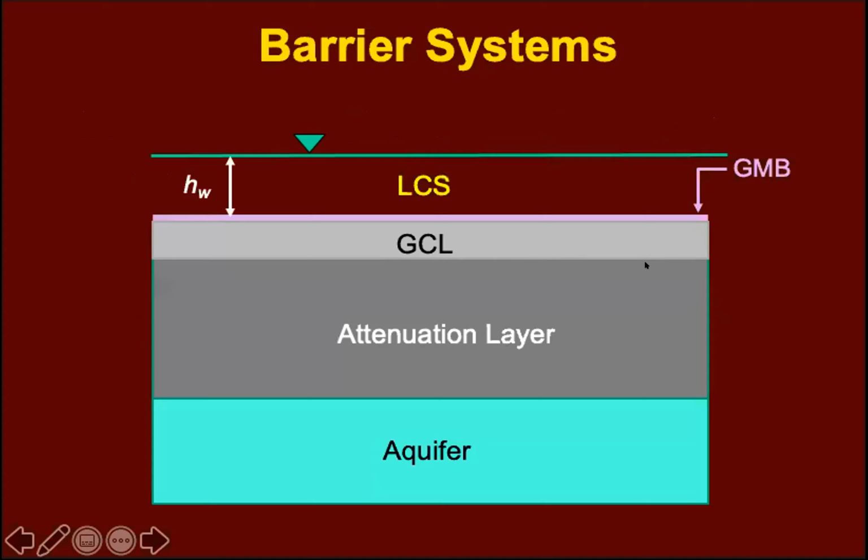The presence of a leachate collection system is not enough to prevent liquid from seeping down the soil layers present beneath the landfill, so it will result in contaminating the surrounding environment. So a barrier system is designed beneath the landfill to contain this leachate.